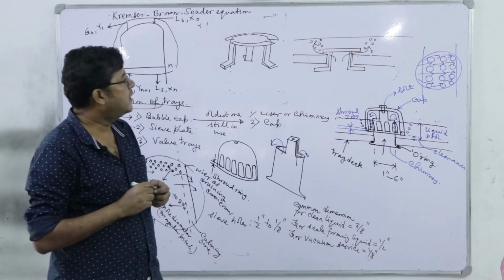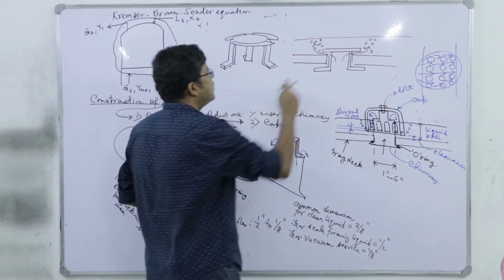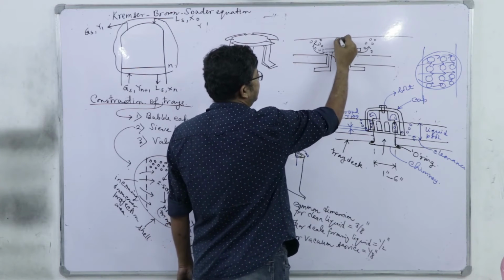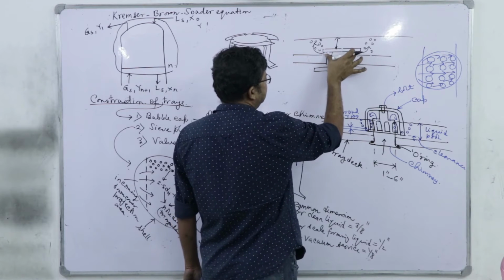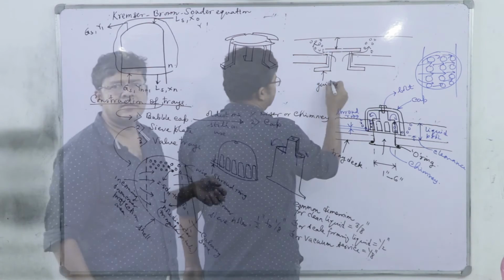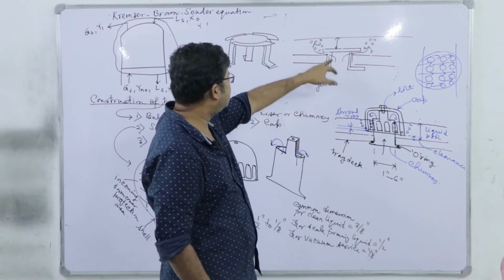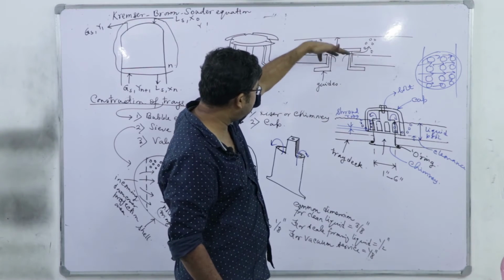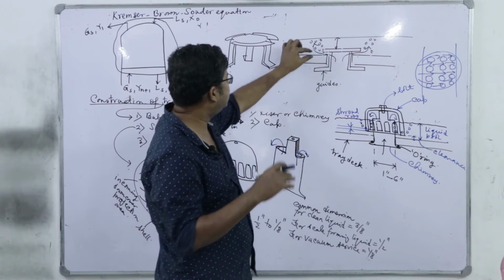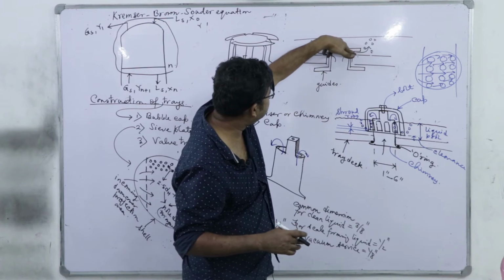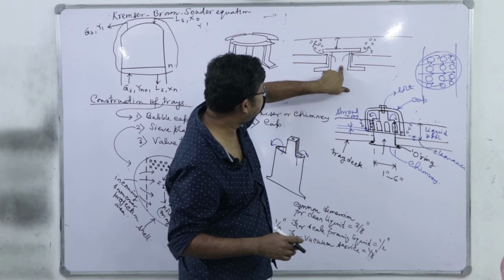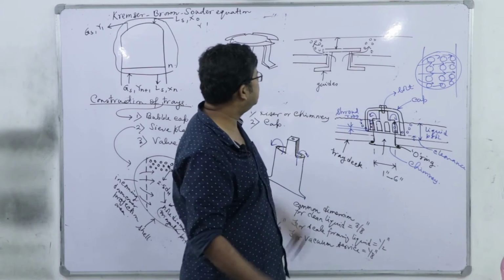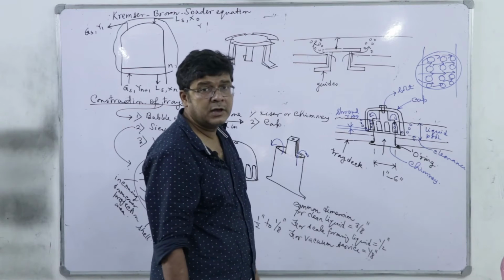Now, what happens if I have a high gas velocity? So, let us say initially the valves are all closed, right, because of the pool depth and the respective static pressure. These extension plates are called guide vanes, guides. What happens initially when we have zero gas velocity, this extension disk has contact with this tray deck. Now, we have charged the gas, right, at a definite pressure. So, this disk will pop up, allowing the gas to flow out into that pool of liquid. The point is,